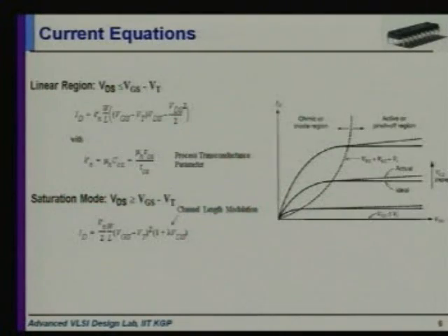But see, in the linear region, that is in the ohmic triode region, we can see that there will always be a finite slope. As there is a dependency of the ID on the VDS, this is not the output transconductance of that particular amplifier. In this region, mainly the MOSFETs are used as a switch, and that conductance, that is delta IDS by delta VDS, is primarily taken as the on resistance of the switch.